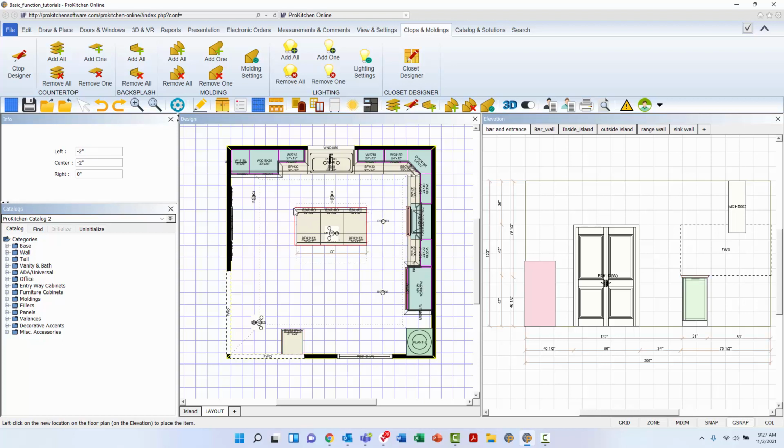The third option in the right-click toolbox is Rotate. This option is only available to select and utilize within the plan view. Once selected, you may either move the mouse to rotate the countertop manually, or you may also type in the required rotation value, then tap Enter on the keyboard. Note, if there are any obstructions for a rotational value, the countertop will not rotate beyond the obstruction and must first be moved to allow for the rotation.